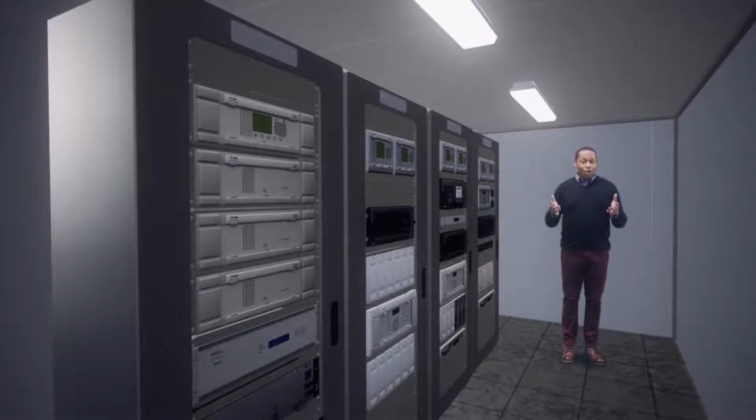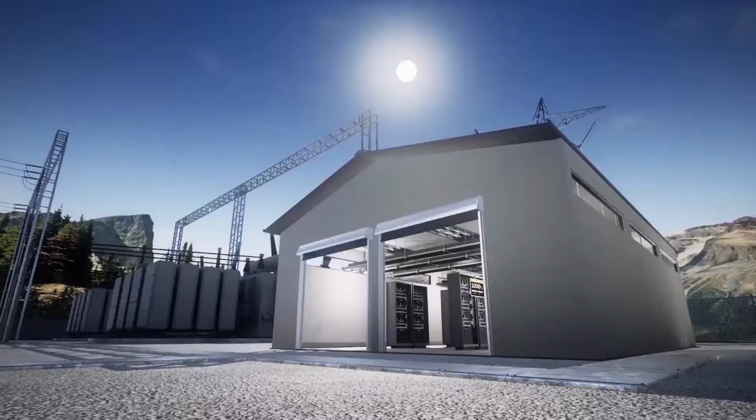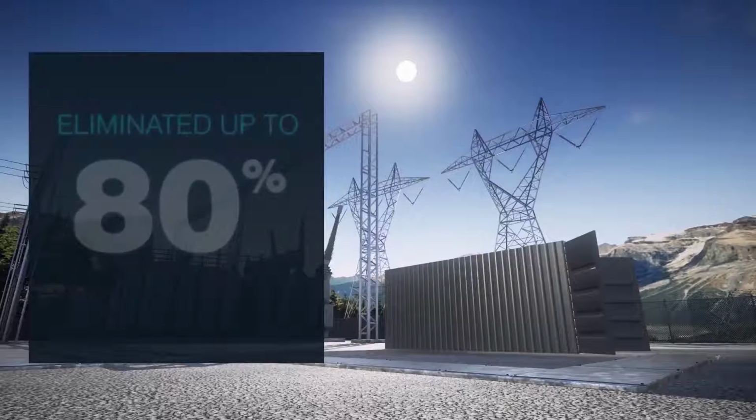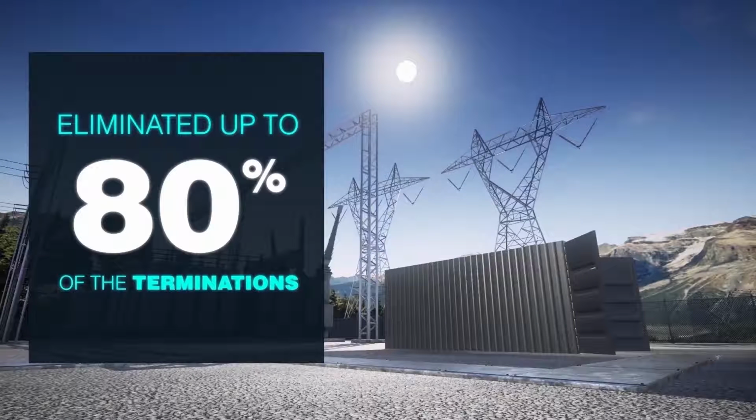This room just got a whole lot smaller, didn't it? In fact, it's about half the size of the room we just saw. The total substation footprint has been reduced by about 50%. This is because we eliminated up to 80% of the terminations by keeping the control and measurement wiring in the switch yard and only bringing fiber optic communication cables to the relay room.